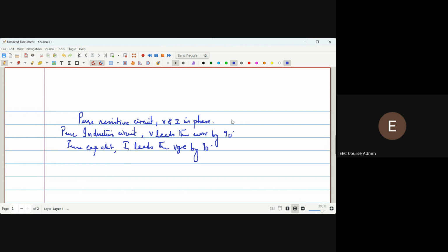In a purely resistive circuit, since the voltage and current are in phase, the angle involved in the impedance will be 0. So what will be the power factor? 1, ma'am. Power factor will be unity in the case of a purely resistive circuit. Then what about these two? 0, ma'am. And for other composite circuits, depending upon that angle which lies between 0 and 90 degree, you will have a finite value for this power factor.